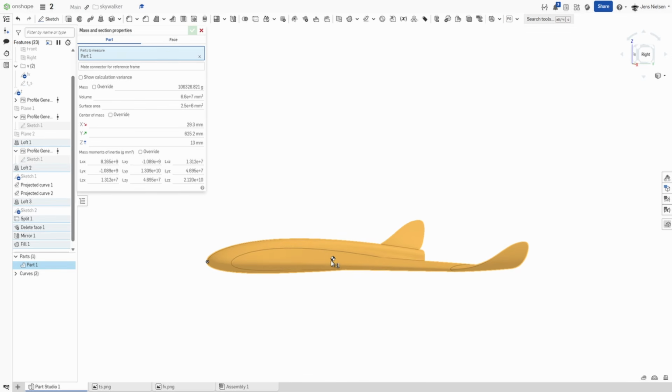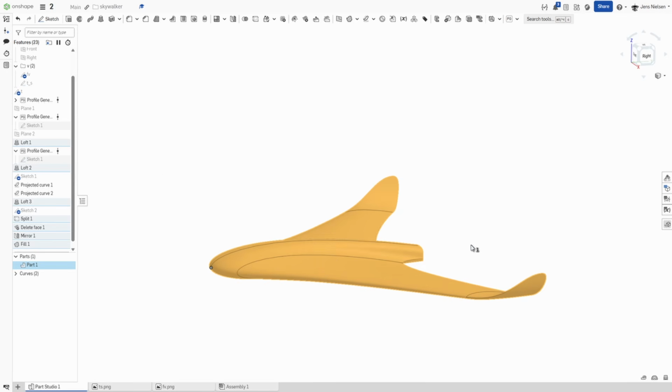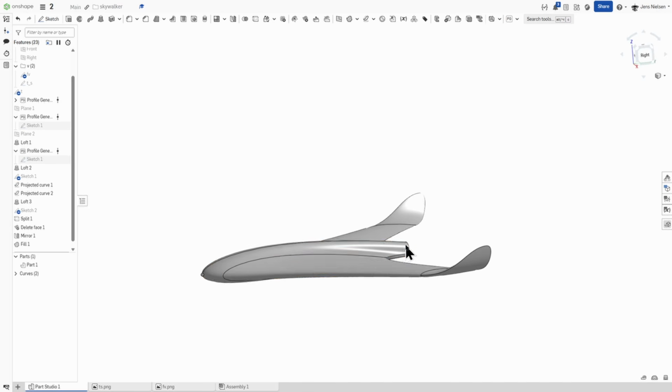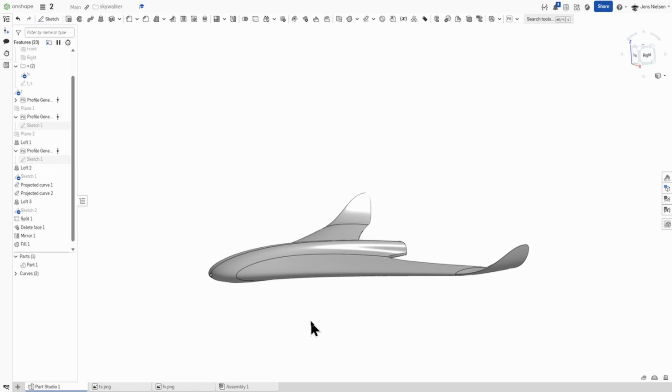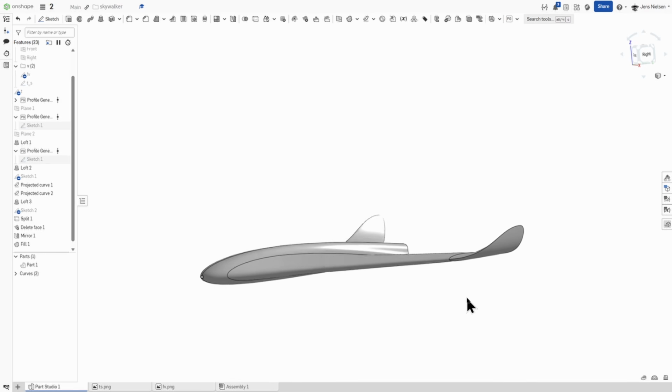And this helps me to fine-tune my design, because I want some compartments for the battery, the engine, the RC components, and by strategically positioning the components within these compartments, we can significantly change and fine-tune the center of gravity of our fixed-wing drone to meet our specific needs.